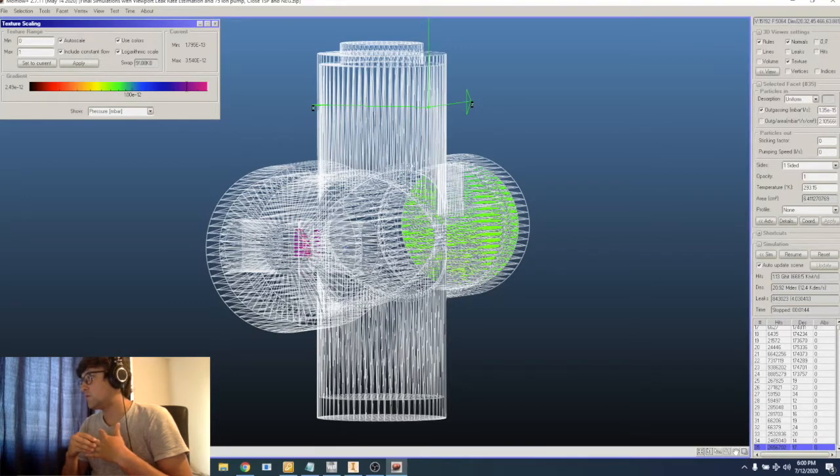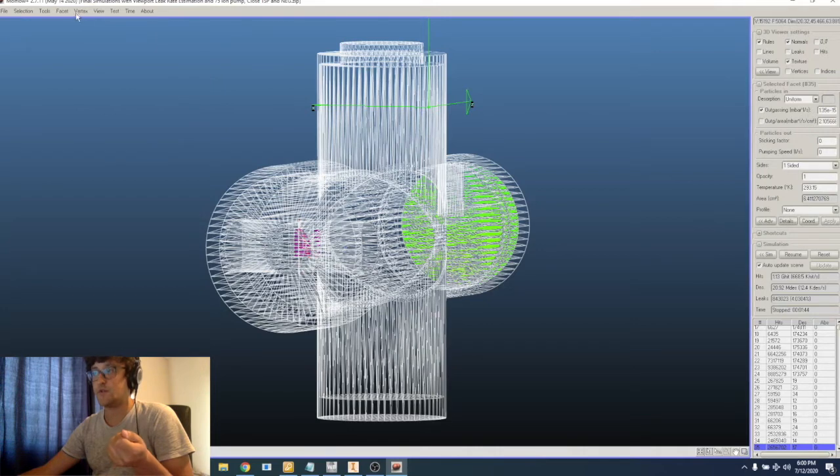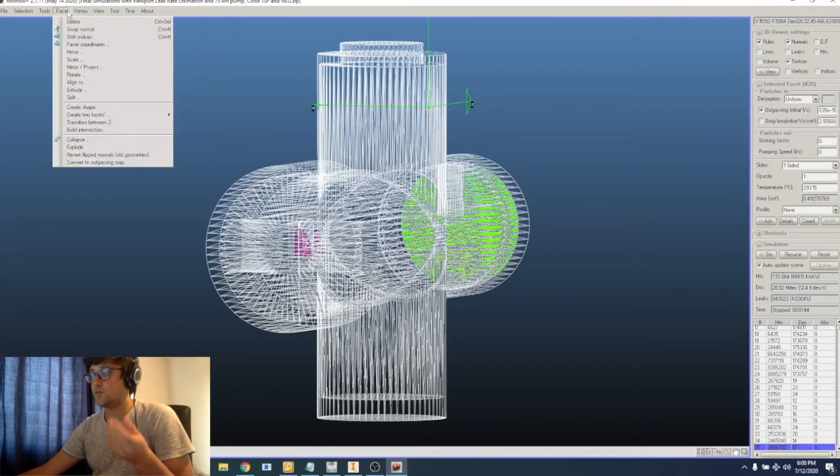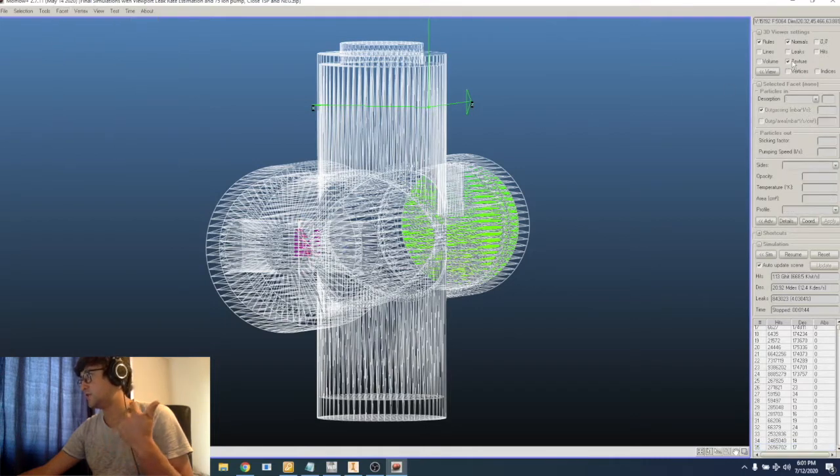So to recap, MolFlow is a tool you can use to simulate ultra high vacuum systems. It basically simulates any system in the molecular flow regime. That's why it's called MolFlow. You want to make a simplified geometry of your system that you can import easily, and then you're going to want to reverse all of your normal indices. Once you've imported it, you're going to want to click on textures and normal in your 3D viewer settings.